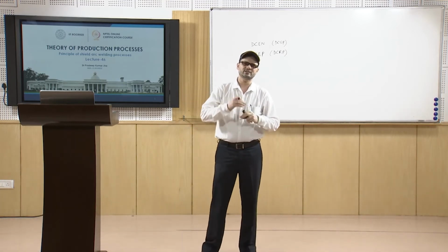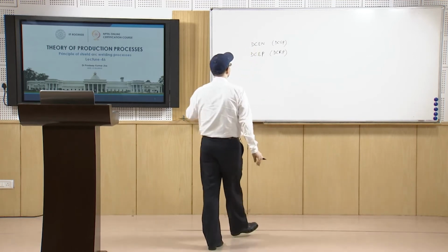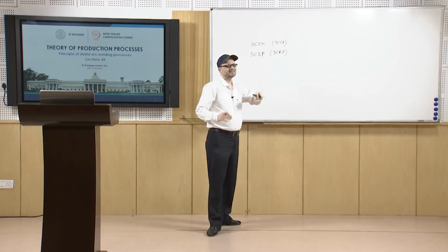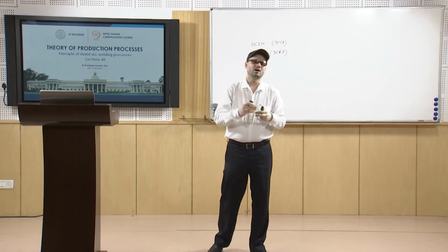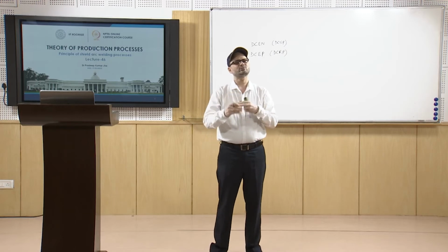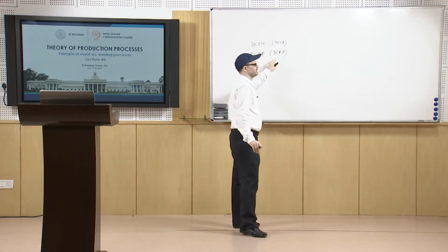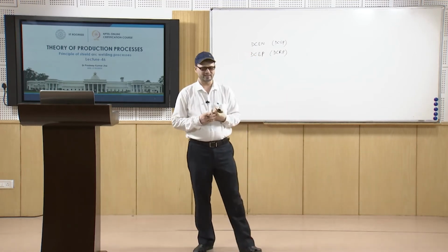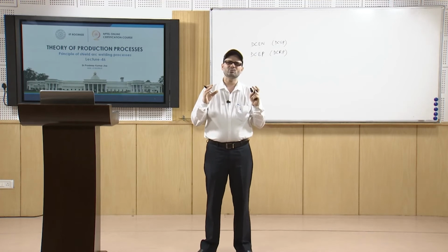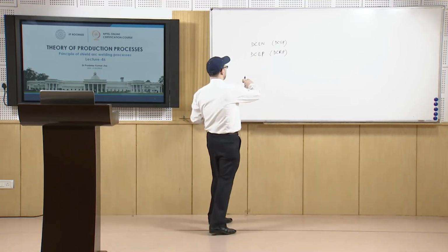In those cases, if you use the straight polarity, or electrode negative and work positive, there will be chances of deformation and an uneven weld bead structure. So that is why in those cases you go for the reverse polarity, where maximum heat will be generated at the electrode itself. And when we talk about AC systems, in the AC system you have a change of flow